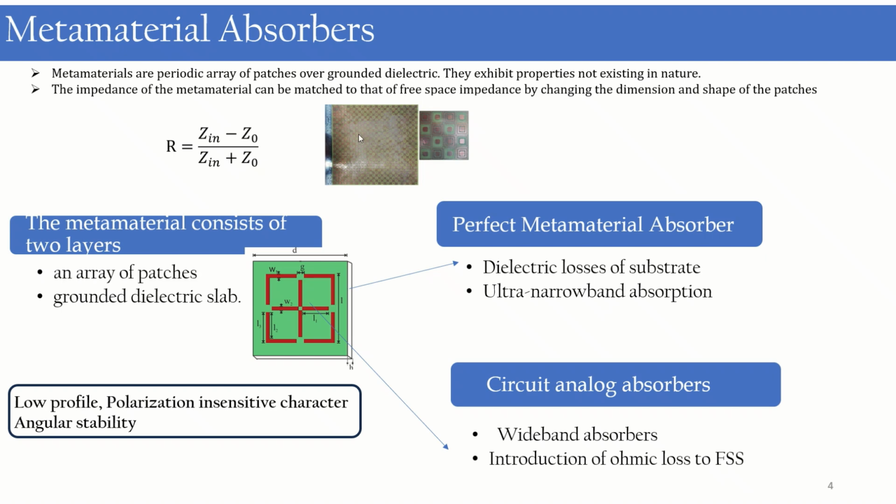In a metamaterial structure, we can manipulate the size, shape, and dimensions of these patches so that the impedance of the structure is matched to that of free space.